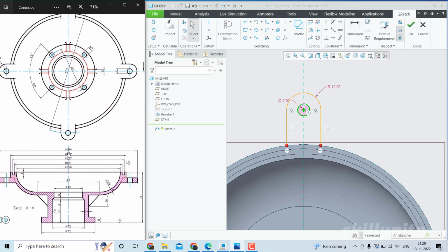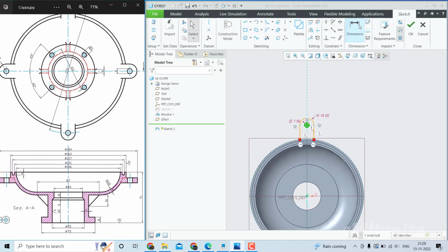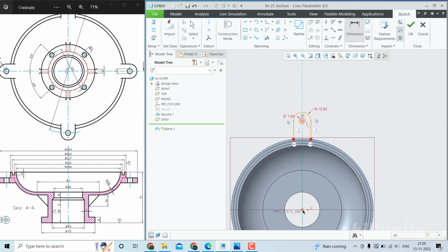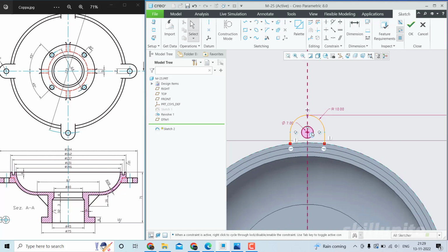As I told, we have this PCD available. So for that, we need to mention the dimension exactly up to this end. When you are creating, mostly it won't come. There is no end point. For that, let me create a point exactly here. Then I can use that endpoint for giving my dimension. So this is 194 by 2. So the shape has been taken now.